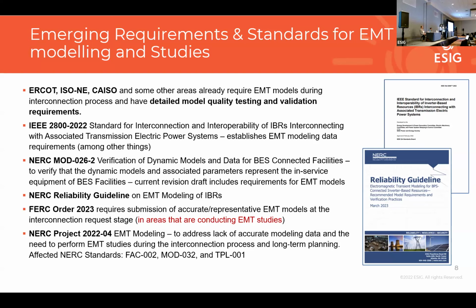I put this in red because this requirement applies only if the area is actually conducting EMT studies. But as I mentioned in my earlier slides, this is too late to collect EMT models if you need a study. So I would encourage everyone, if you work for a system operator or transmission owner, to start thinking about EMT modeling way ahead and collect models during the interconnection process, regardless of whether you're doing EMT studies or not.